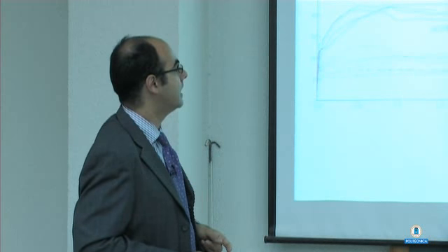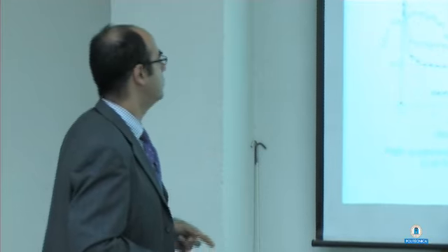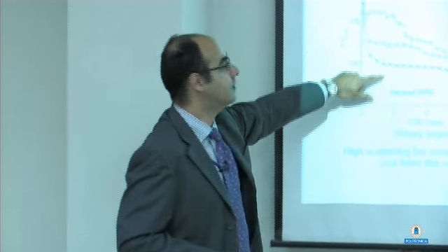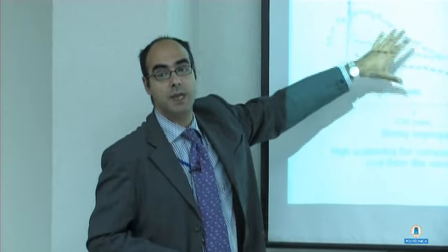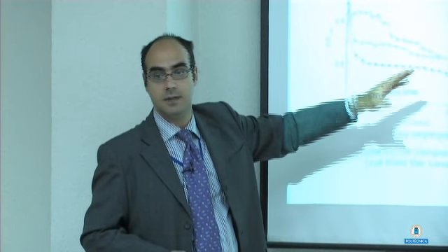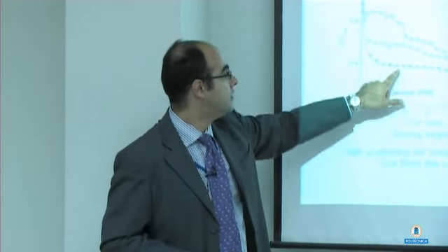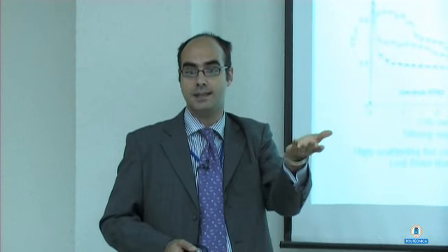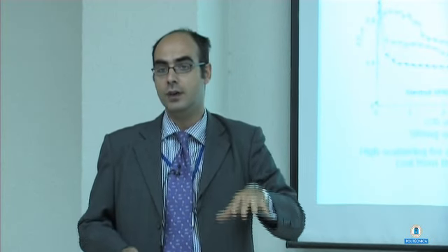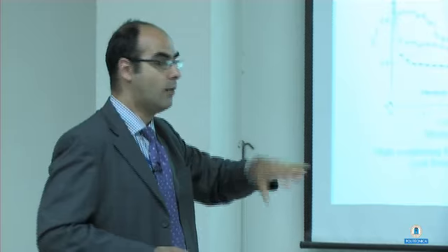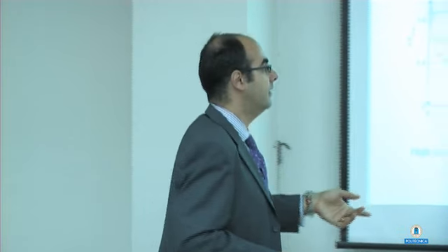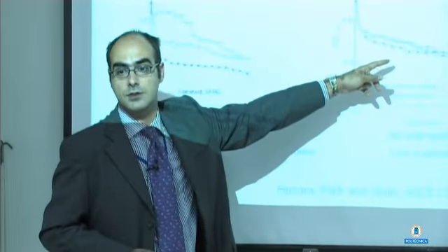And we made some similar tests on the specimen that I showed you before. You can see here, these are the results for vibrated concrete. These 3 beams come from the same slab. They were 1, 2, 3 beams. And this one was tested upside down to casting. So in a vibrated concrete, due to the vibration, the fiber settled down, and when you test upside down, you don't have. And these are the results for self-consolidating concrete.